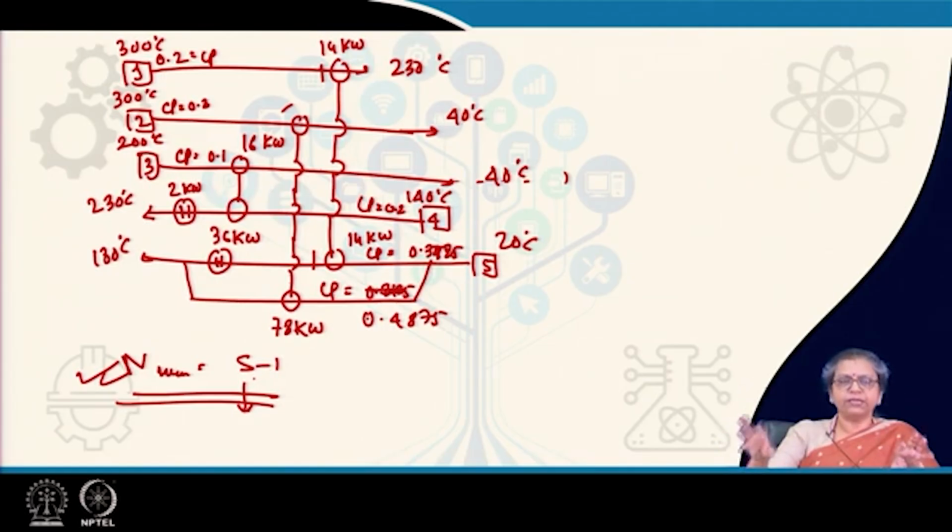Design the 2 separately. For designing the hot section and the cold section, represent both of them in the form of grid diagrams. Place the heat exchangers using the tick off heuristics, and whatever unbalanced thing remains, just compensate it by the utilities, and you will find that if you have done it correctly, then you will not need a cooler in the cold section, you will not need a heater in the cold section, you will not need a cooler in the hot section.